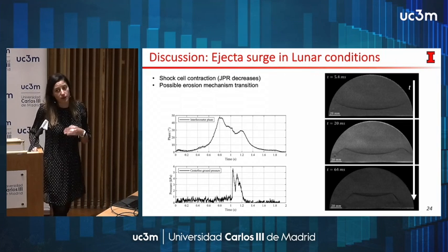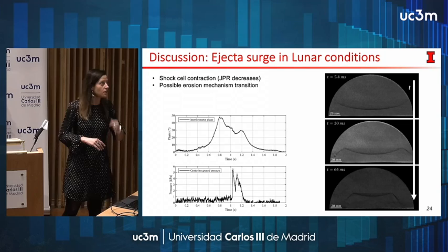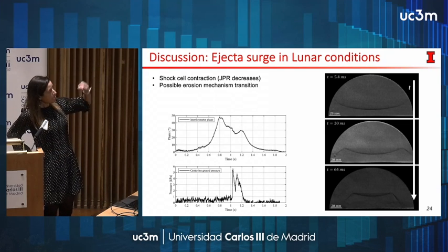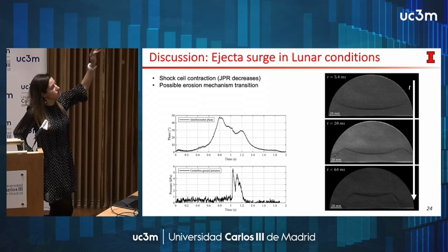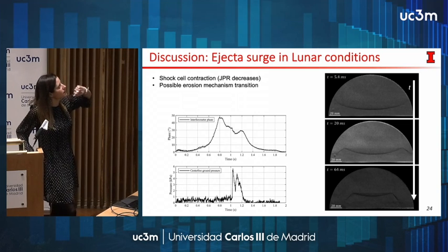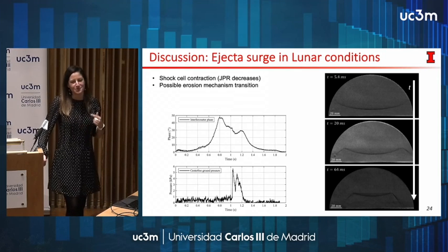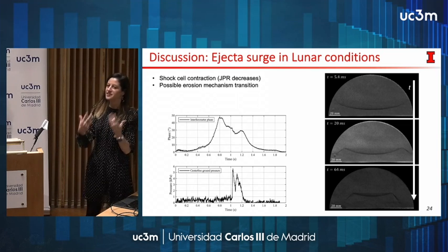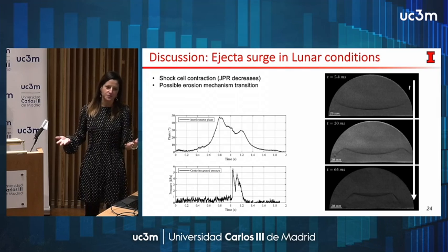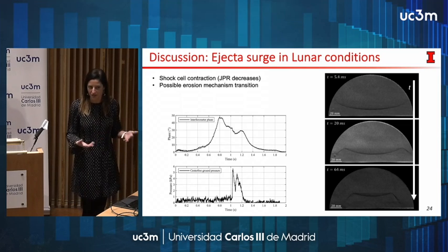So you have liquefaction. If you look at the same thing in the lunar case, you don't have this strong impingement because remember there is a surface shock, right? So it's kind of protecting the soil. But what I didn't tell you, and why we start with a steady erosion and then somehow transition to another mechanism of erosion, is that our vacuum chamber is small, and that is something we cannot do much about unless someone wants to make a donation for a huge vacuum chamber. And if you are putting air in a vacuum chamber, of course you are changing the ambient pressure. For the lunar case, the pressure is much lower, so the effect is significant, while for Martian, it doesn't really matter.